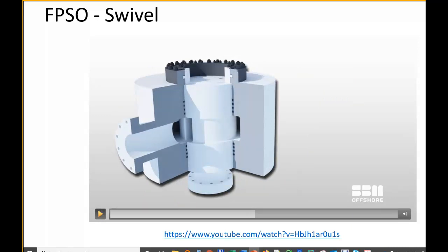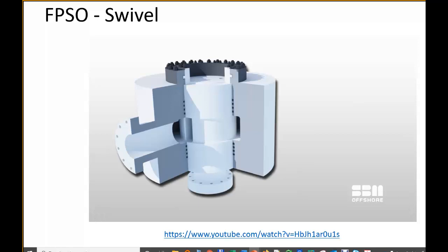For example, if you were expecting some rate of water or some rate of sand, and then you are getting more sand than what you are supposed to get, then you're going to get erosion, because the whole swivel is tightly dimensioned for the rates and the capacities that you have. So if for some reason you start getting too much water from the production fluid, then you have too much liquid to flow through the swivel. That can lead to erosion, to all kinds of problems, to leakage. So they have to restrict the flow rate through the swivel.